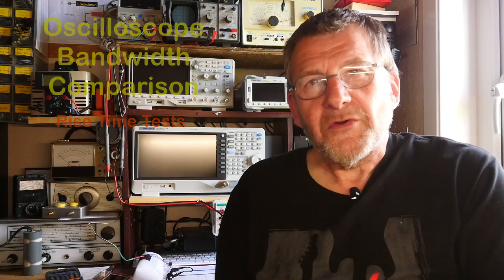Welcome to another video from Lockdown Electronics with me, Bill, and this time we're going to have a bit of a shootout in terms of oscilloscope bandwidth, and we're going to do it by measuring the bandwidth of the scopes using the very fast rising edge of a square waveform. Now, a lot of people will say that's a much better method of measuring bandwidth than the normal method of looking for the 3 dB down point.